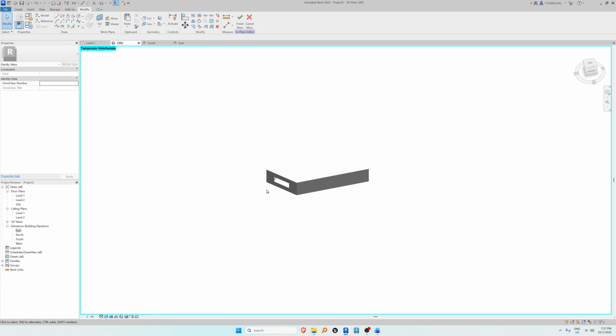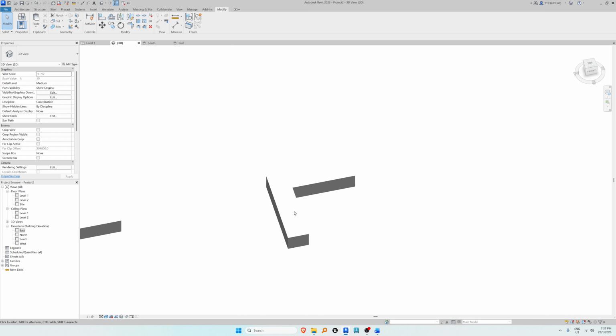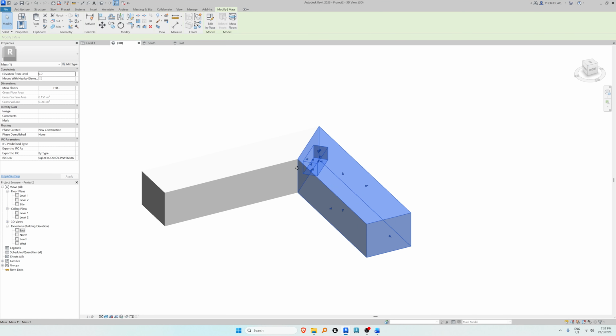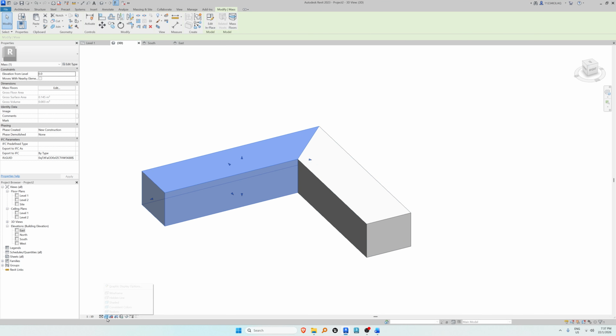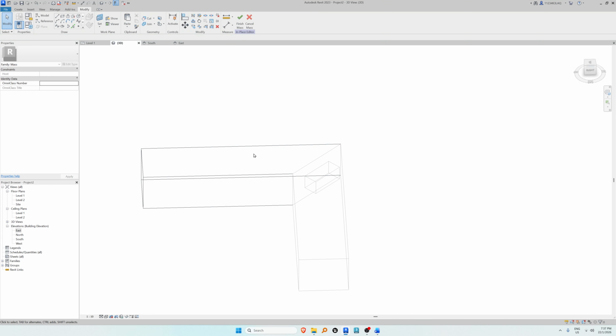So now we will have one piece of wood that fits in there and then connects to that one. We can always finish this, reset. Same for this one, right? Let's change this to wireframe so we see what's happening. Let's cut out this one, edit in place. We're going to set our work plane, pick line first, sorry, and then set your work plane. We will set it to this face, right?